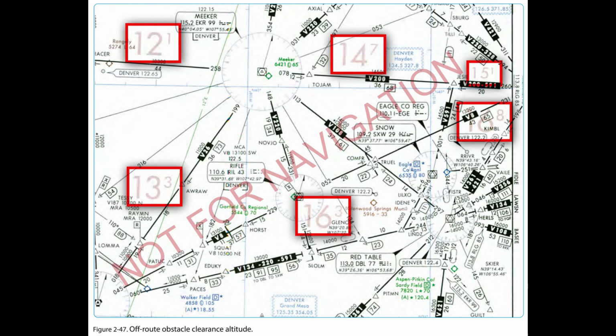When departing an airport VFR intending to or needing to obtain an IFR clearance en route, you must be aware of the position of your aircraft relative to terrain and obstructions. When accepting a clearance below the MEA, MIA, MVA, or the OROCA, you are responsible for your own terrain/obstruction clearance until reaching the MEA, MIA, or MVA. If unable to visually maintain terrain/obstruction clearance, pilots should advise ATC and state intentions of the flight. Figure 2.47. End of page 2-27.